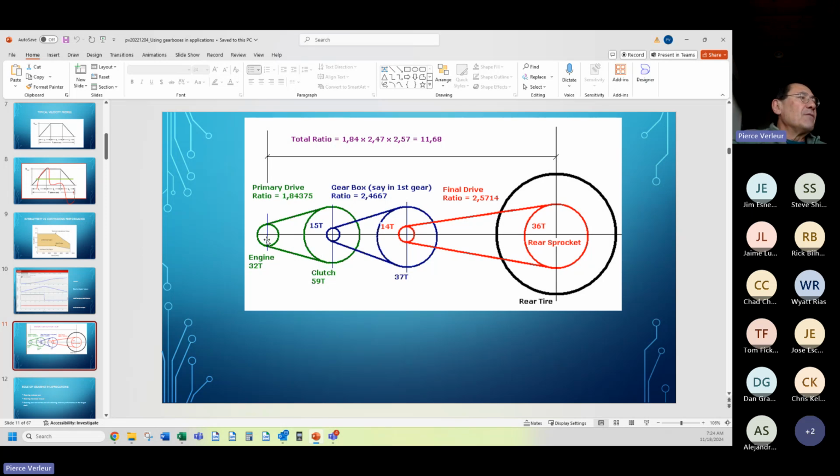So in a gearbox, you may have 1 ratio reduction, we call it single reduction, 2 ratios of reduction, this is double reduction, and this would be triple reduction. And then you have your output shaft here, which is your target shaft. This is a triple reduction gearbox. The ratio of the total is the ratio of all 3 multiplied together.